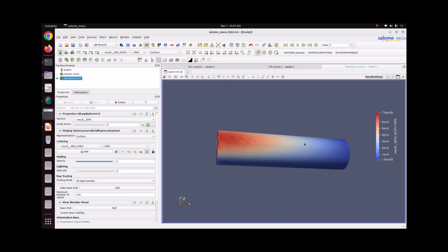That is because we have taken only a linear element. To make the mesh finer and convert that element into quadratic, we can get an accurate result compared to the analytical. So this is the way we can compare. Now we are getting 7.4. Just convert our element into quadratic, we'll get a very close value to the analytical results.